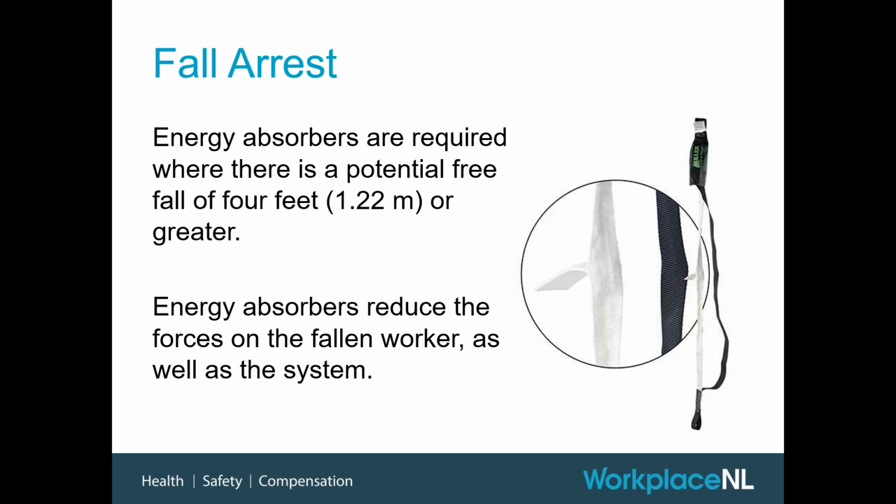I also just wanted to highlight that we do have a new CSA standard out in recent years around the classes of energy absorbers. We used to have E4, E6. Now we have this new class called Y. So again, just a little bit of food for thought for you all if this is news to you. These new Y class absorbers no longer have specific weight requirements that were in place for the E4 and the E6.